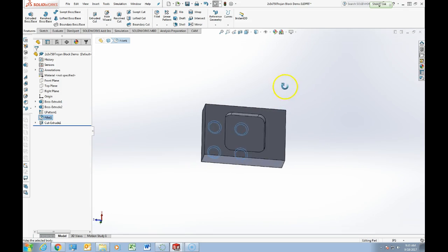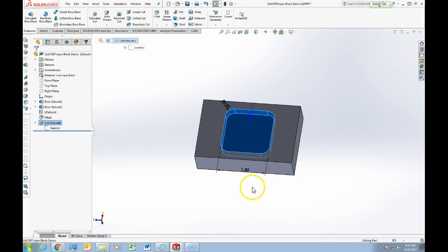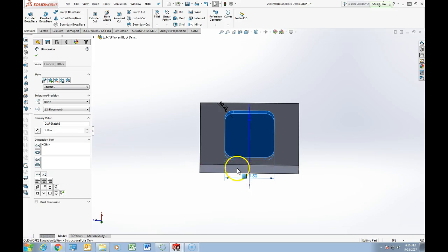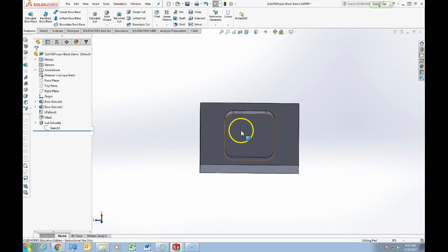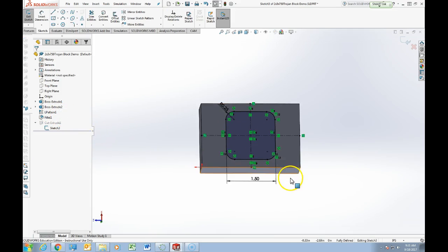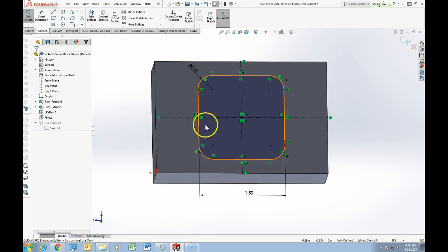But notice the underside here isn't exactly right either. I cut extrude. I could modify this and say, hey, that needs to be 1.5. Instead of 1.5 now, if this is 3 going that way, it would actually have to be 2.5, I think, going that way. And I didn't change anything else. But depending on how you sketched out your bottom, your extrude cut, this would be an awesome application for that thing about equations we had learned about before in one of the tutorials.